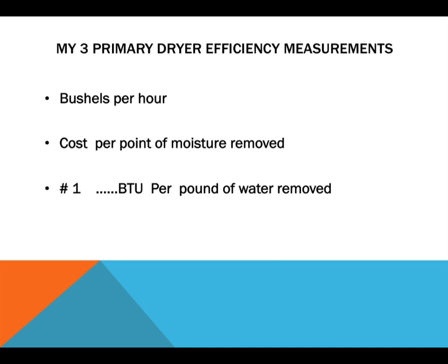And last but not least, actually my number one efficiency measure, is the BTU per pound of water removed. How efficient is that dryer in removing water from the grain?